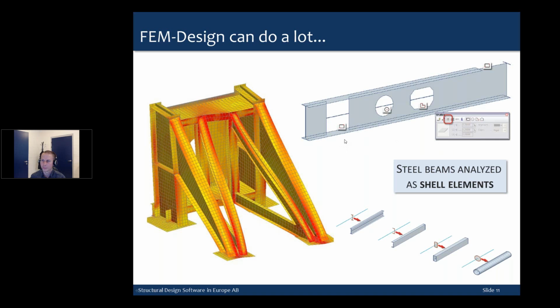Giuseppe, if you run a second order analysis, no, you cannot set up buckling length in shell elements. That you cannot do. In the next version, we will have buckling length for the concrete walls. You can define and set it together with shell elements to do a first order analysis of a shell element with buckling length. But this is in FEM-Design 2017, which will come hopefully in December. So it's not something we have today. That will come together with plasticity in the model.